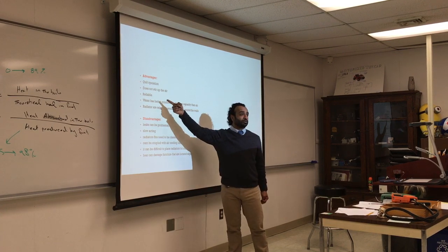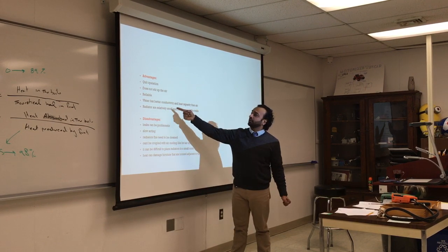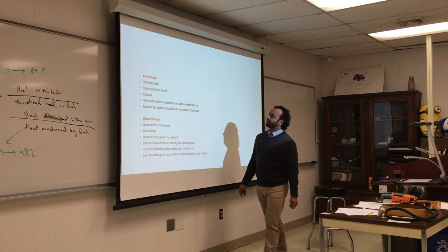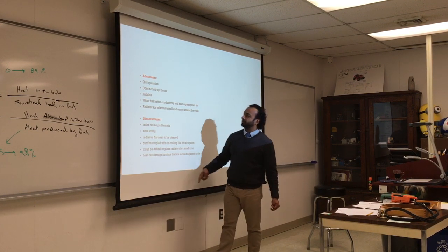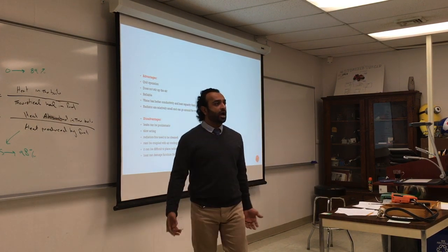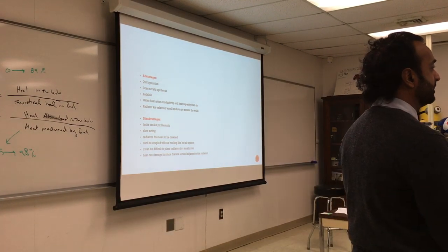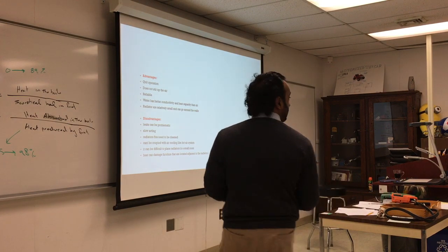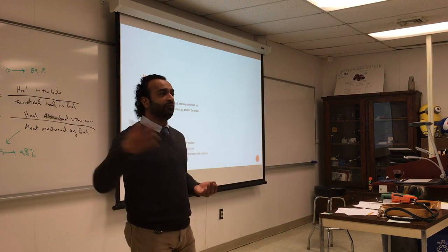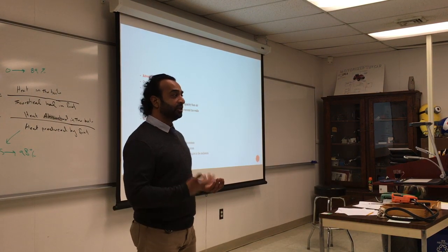Again, that's a very questionable term. Reliable, what do you mean by reliability? And water has better conductivity and heat capacity than air, which means that I can take a lot of heat from the boiler and deliver it to the living space. Meanwhile, the air does not have the same heat capacity, so I have to pump air continuously into the room.